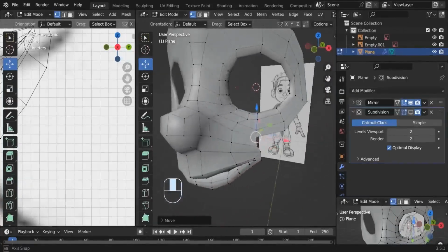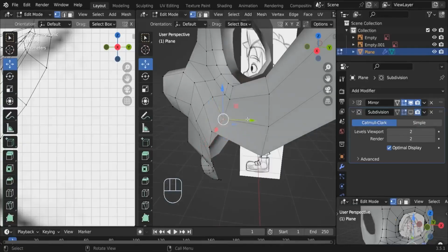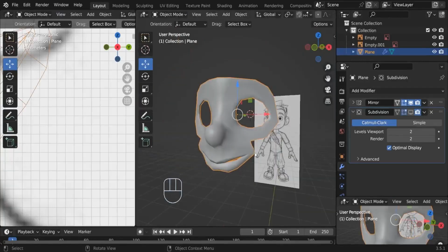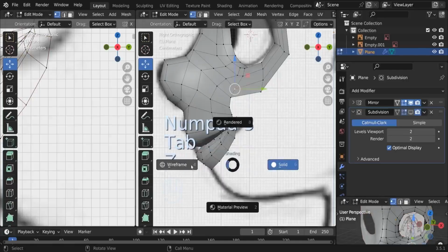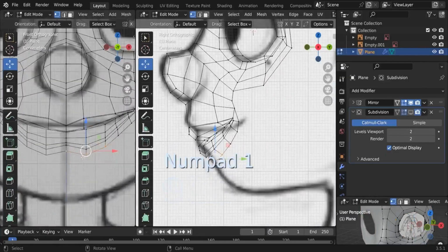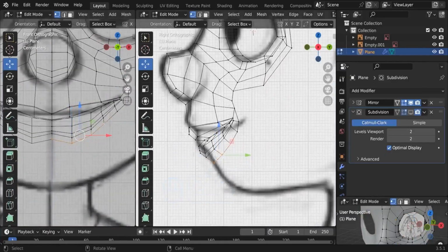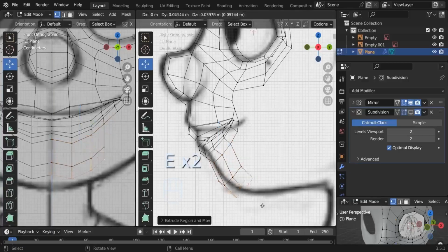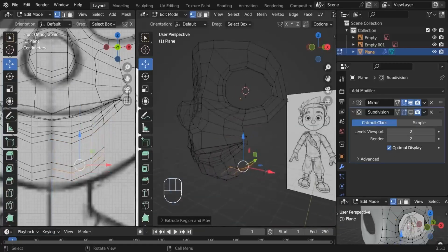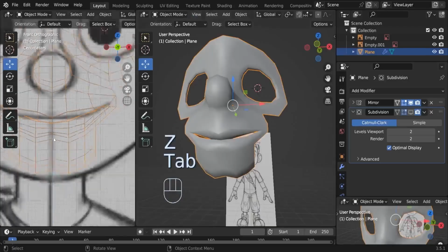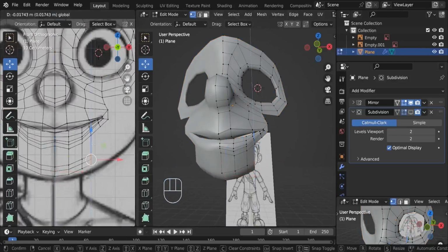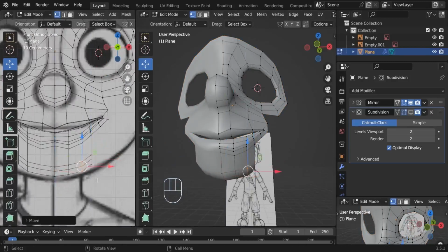Let's investigate our geometry. So whether we have to push these outside or we can take these inside. I think that is the right way. Alright, so let's work a little bit on the chin. So I'm gonna press 3 to go to the side, and can switch to the wireframe, and let's select these 3 vertices. Let me check. We can go here to the front to make sure that we are selecting everything. Can also include this 4th reference. Can extrude it down and extrude like this. Okay, let's check that. Seems to be reasonable. Here on the front we can simply align this vertex with the rest. Let's take this one a little bit down to have that circular face.